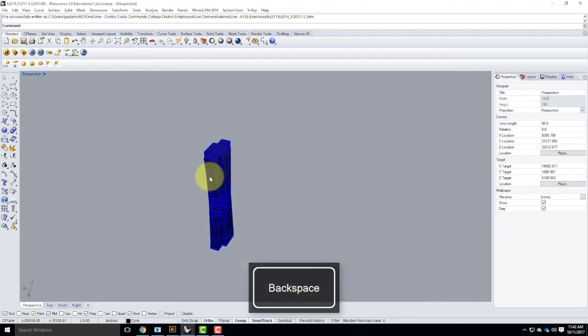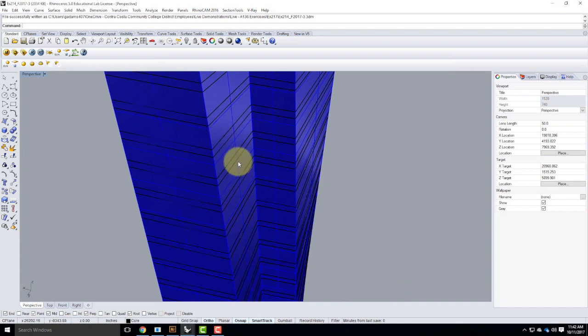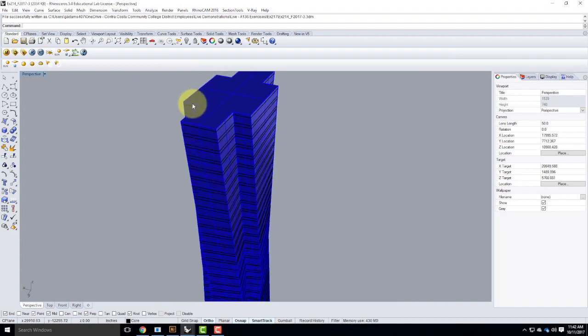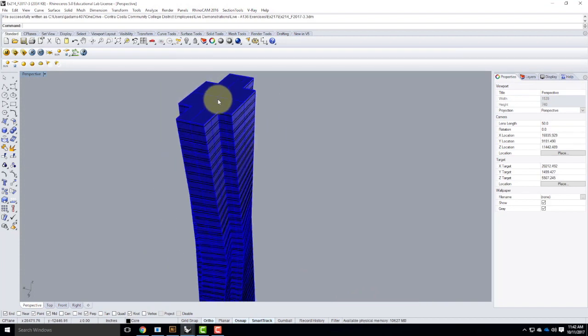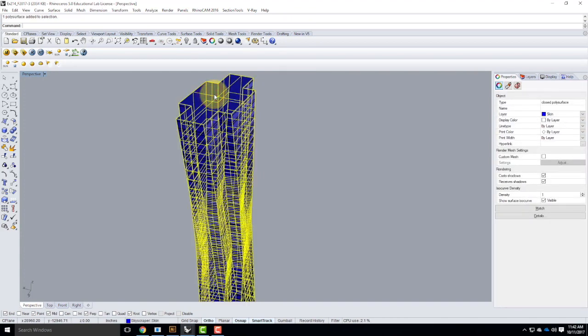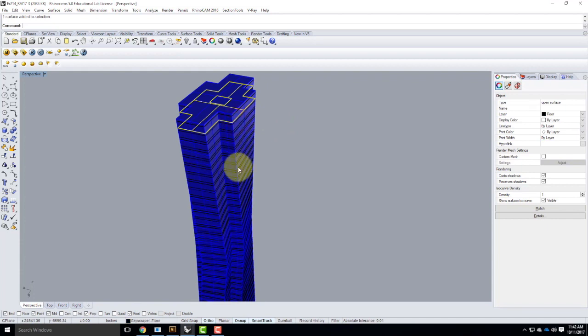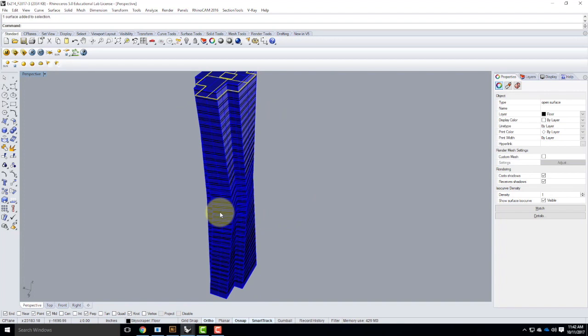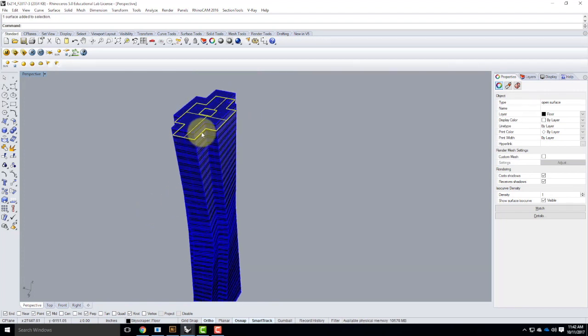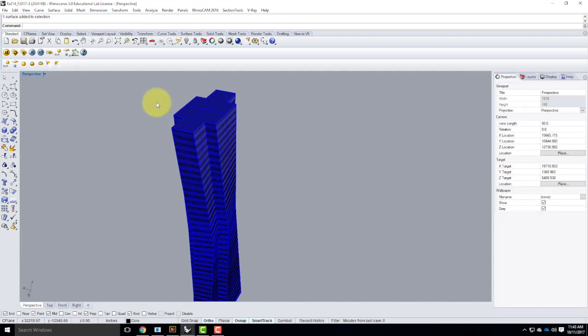And I'll click Save. So in the interest of exploring what's going on here, as I look at this particular model, I have the outer skin of the building, and then I have all of these individual little floors that are representative of the building. If I were to take this over to 3D print, the 3D printer would have a really hard time with these floors because they're not closed, watertight objects. That's what it likes.